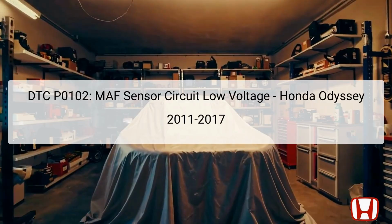DTC P0102 indicates that the mass airflow (MAF) sensor circuit is reading low voltage. The MAF sensor plays a crucial role in monitoring the amount of air entering the engine, helping the powertrain control module (PCM) adjust the air-fuel mixture for optimal performance and emissions.